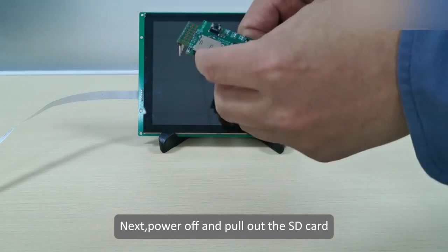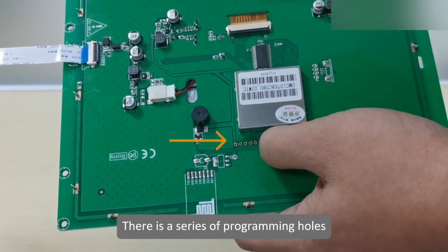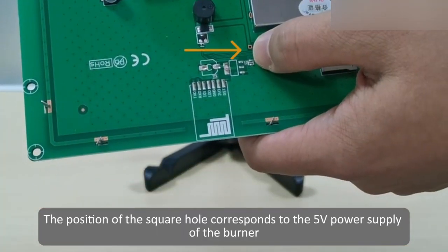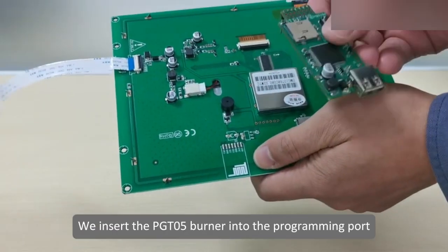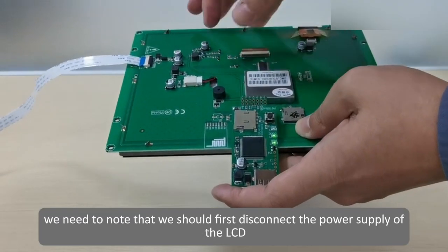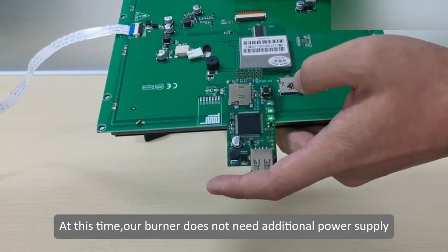Next, power off and pull out the SD card. Then, let's look at the back of the screen. There is a series of programming holes, which correspond one-to-one with the pins of our burner. The position of the square hole corresponds to the 5-volt power supply of the burner. We insert the PGT05 burner into the programming port. Before programming, we need to note that we should first disconnect the power supply of the LCD. At this time, our burner does not need additional power supply.